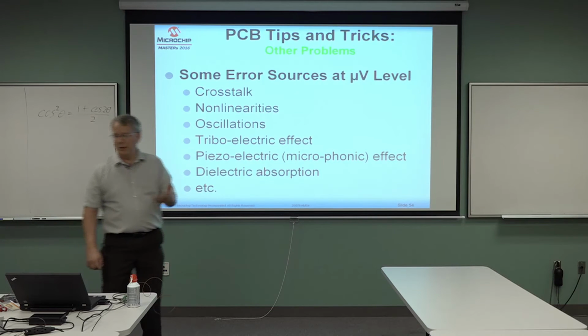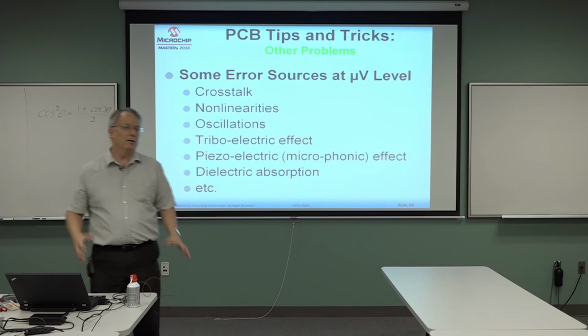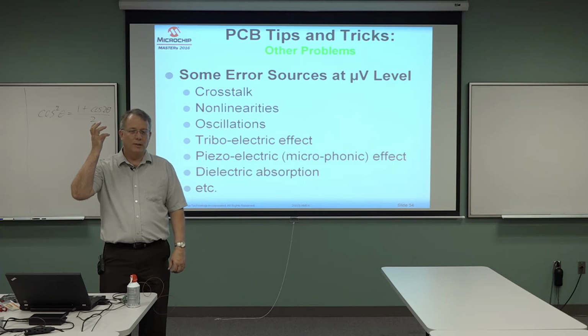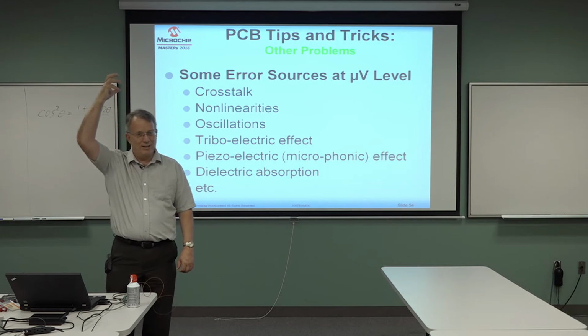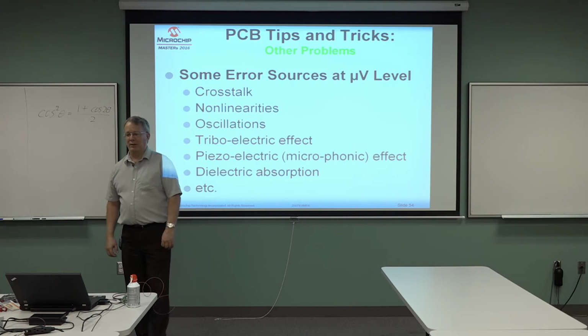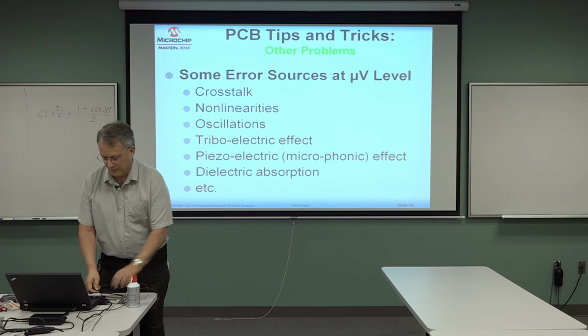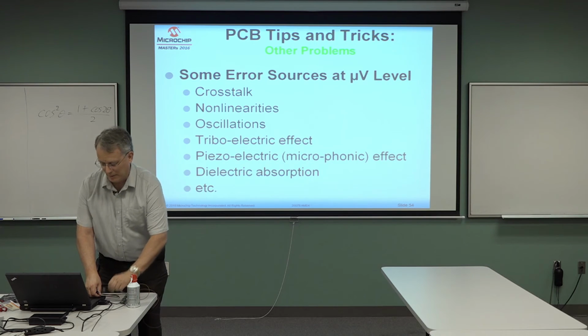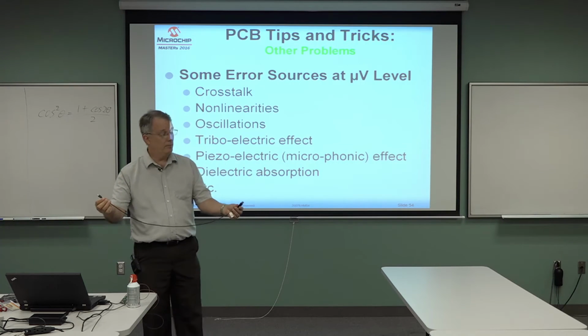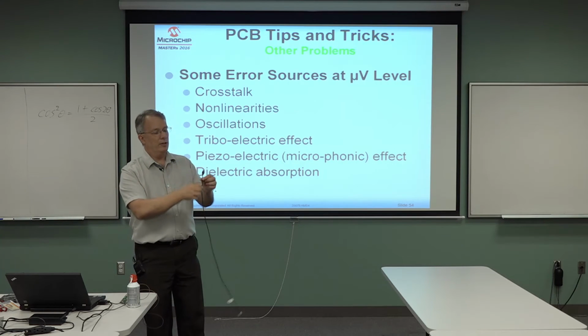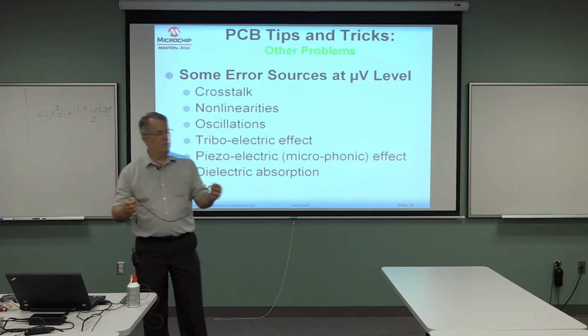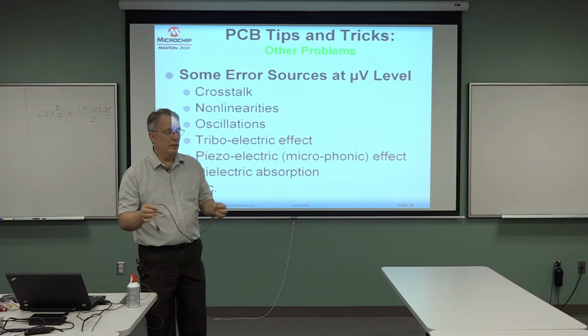Triboelectric effect. If you look up the triboelectric effect on the internet, you'll probably get an explanation about how this is static electricity, and they'll talk about the birthday party trick of rubbing a balloon in your hair and having your hair stand up. Yes, that's true. That is the triboelectric effect. The way it applies to what we're talking about may not intuitively seem like the same thing, but it is. I'll take this USB cable as an example. If you look at it, you have the insulator on the outside. We know that we have a braided shield on the inside, and then some more insulation, then a center conductor, just like a coax in many ways. And this will have multiple conductors because it's a USB cable.